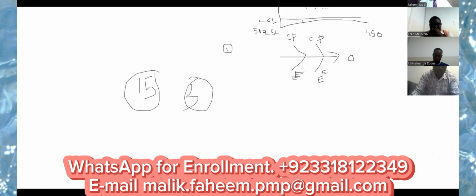Then we have a flow chart. A flow chart is telling us the sequence of the process. For example, when the welding joint is complete, first we will do VT. After that, we will go for a surface test or subsurface test. We will perform DPT, then MT, and then UT. There is a sequence. A flow chart will tell us the sequence of the process.